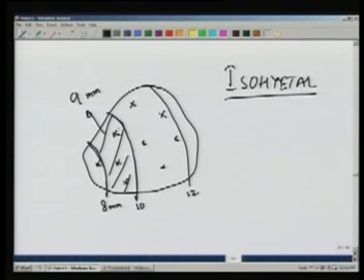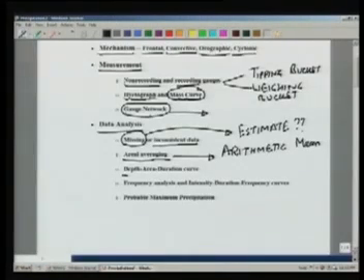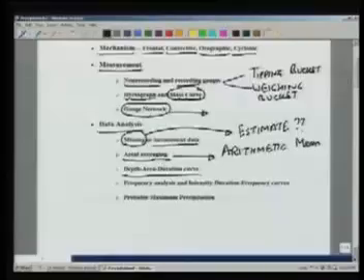and by summing up the area and the rainfall over the respective areas, we can get the average rainfall over the area in terms of P bar, and suppose P1 and P2 are the surrounding isohyetal values, and A is the area between them. Then we simply sum up the average precipitation into the area for all the isohyets in the area. Now once we get the areal average, we can know what is the depth of rainfall over a certain area, and then we can prepare what are known as depth, area, duration curves.